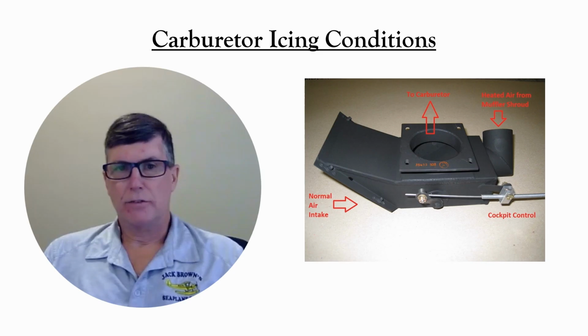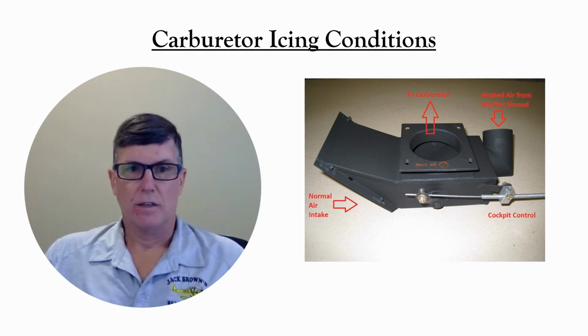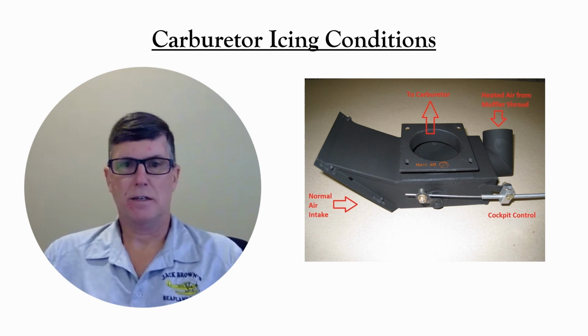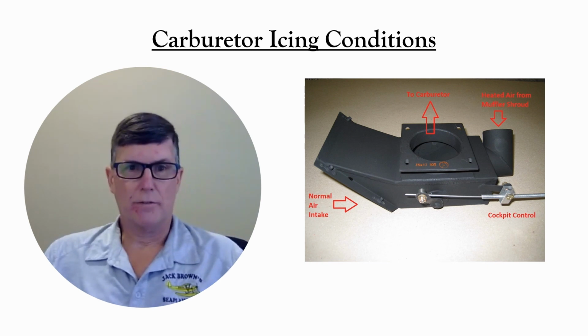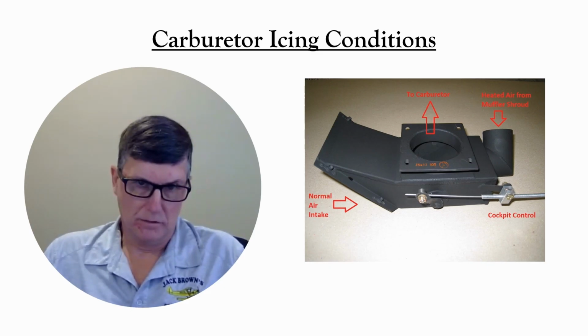If carburetor ice is already there when you select carburetor heat, then the power will gradually increase after that initial drop as that ice melts away. However, the engine may run even a little rougher while it's clearing out that ice.